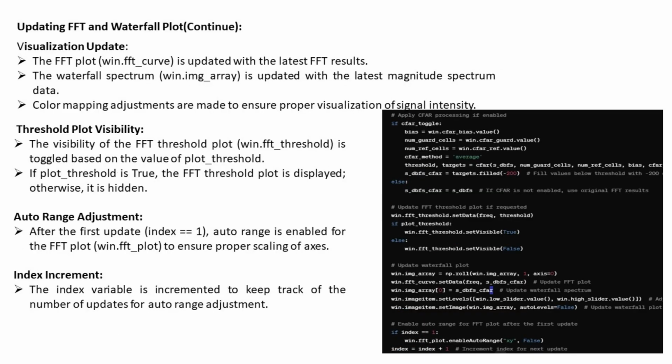Visualization update. The FFT plot, win.fft_curve, is updated with the latest FFT results. The waterfall spectrum, win.img_a, is updated with the latest magnitude spectrum data. Color mapping adjustments are made to ensure proper visualization of signal intensity.